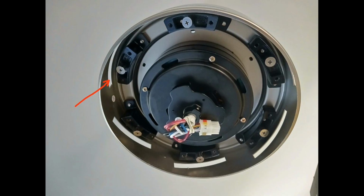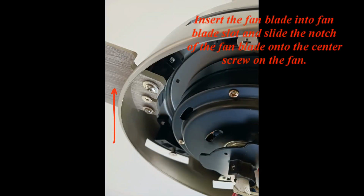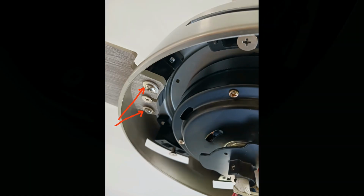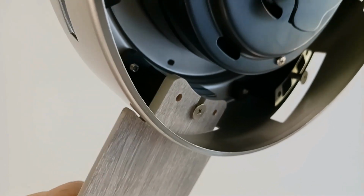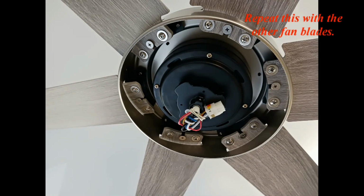Fan blade slot. Center screw. Slots for fan blade screws. Fan blade notch for center screw. Insert the fan blade into fan blade slot and slide the notch of the fan blade onto the center screw on the fan. Secure the fan blade with fan blade screws with washers. Tighten the screws. Repeat this with the other fan blades.